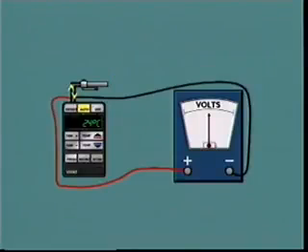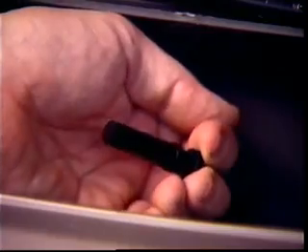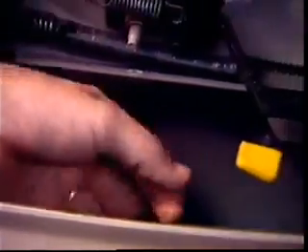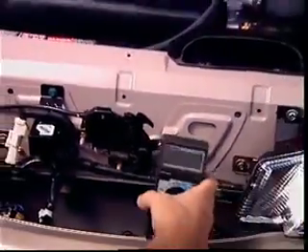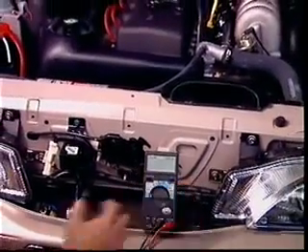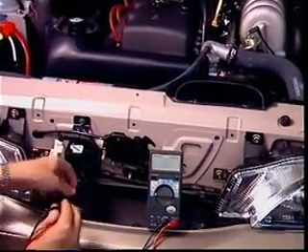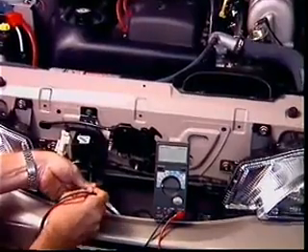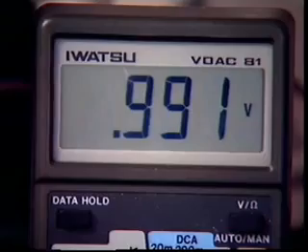When connected into a circuit, the sensor changes the voltage at the electronic control unit. The electronic control unit reads the sensor voltage as the temperature and compares this reading with information stored in its memory. The ambient air temperature sensor measures the temperature of the outside air. It is usually located in front of the air conditioning condenser, where the forward motion of the vehicle and the action of the condenser fans forces air over the sensor.